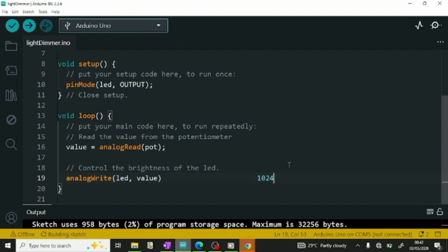This is from the hardware design of the microcontroller. The analog input pin is a 10-bit pin, or let me say it works with 10 bits. So we are getting values from 0 to what? 1023. Counting 0, 1, 2, 3, this one is 1024.